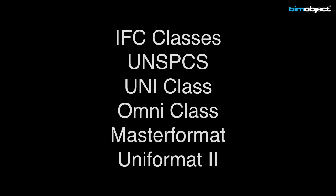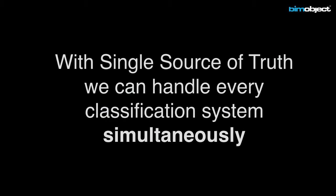So examples of classifications are IFC classes that type the different components to what they are. There is UNSPSC from the United Nations. We have Uniclass, popular in the UK, not elsewhere. Omniclass, which basically is a standard in many Revit applications and in the US. MasterFormat is used very much in the US for specs, and Uniformat 2, and we have more than that. That's just a little bit of an example of what we have.